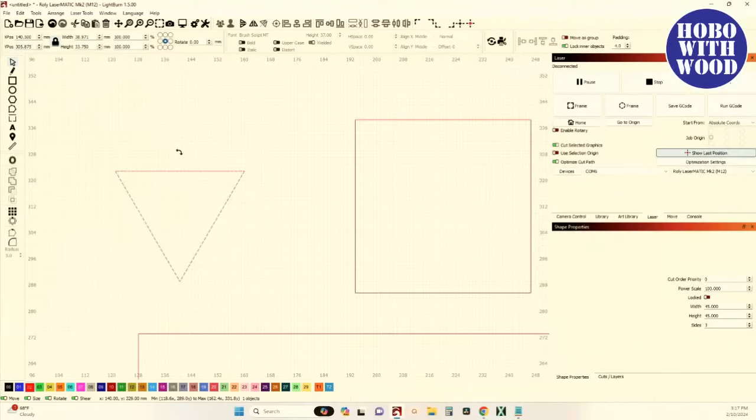But real quick, this is one thing I will point out that is going to be slightly different in 1.6, because we had a couple of people where that dot, and this also goes for the radius tool, made it a little bit hard sometimes to grab some of the other handles that let you control the shape. So in 1.6, you'll hold down Control, and then that dot will show up, and then you can move it, and it goes away if you release Control. Right now in 1.5, it always shows up, but in the future, it'll be a Control option. So you have to hold Control in 1.6, but the functionality is identical otherwise. It's just a matter of getting it to show up.